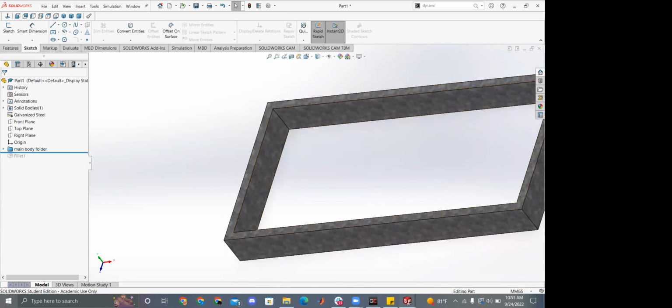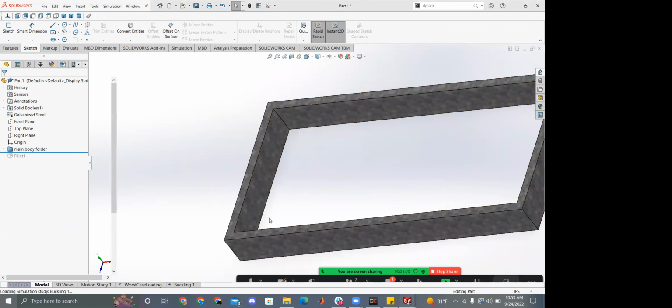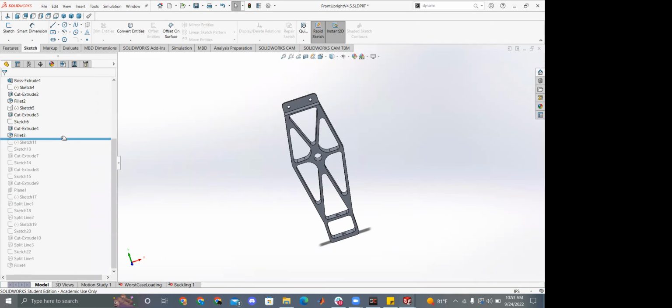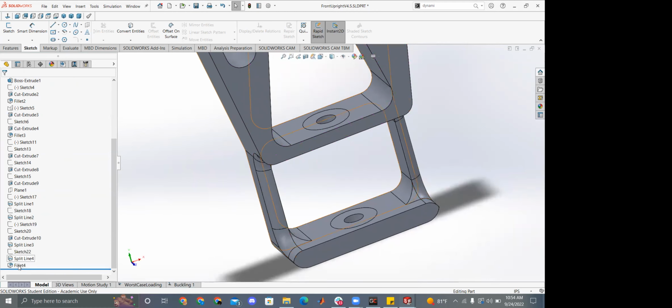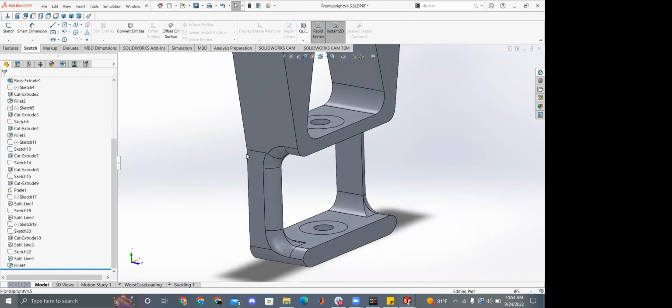This can be useful in a lot of ways. For example, on this old part again, this is a fully complete part. If I want to remove this fillet for some reason, to do work on this part of the upright without that fillet, I can drag the bar from before. And now if I make any feature or sketch, it will put it right at the level of the bar. So it'll be able to insert a feature into your earlier things.